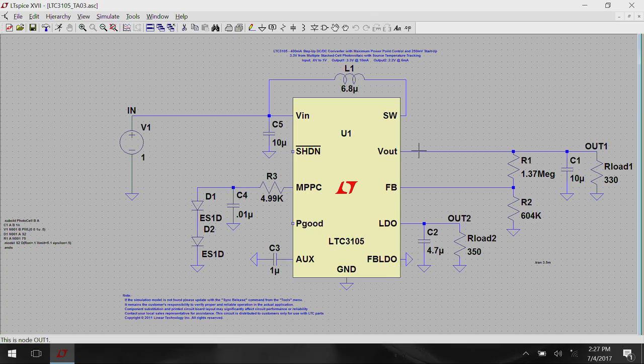V out might reach 3.3, but when different loads are connected to the output of the converter, which could include a microcontroller, the radio, sensors, and other power consuming components, the electronics there will have to work under the constraint that this input will never go below 700 millivolts.